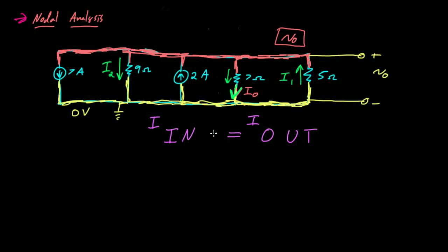And now I'm going to assume that you've unpaused the video, and I'm going to go ahead and do that. I'm going to concentrate on the currents that flow in first. I've got this 7 amp current that is flowing out of my V0 node, so I'll deal with that when I deal with my outward currents. I've got this current that's also flowing from top to bottom, so it's flowing out of my node V0. And then over here I've got 2 amps flowing into my node V0. So I'm going to write this 2 amps on the left-hand side of my equation because it's flowing into my node V0. So 2, and I'm going to leave the A off. I'll just call that 2 for 2 amps.